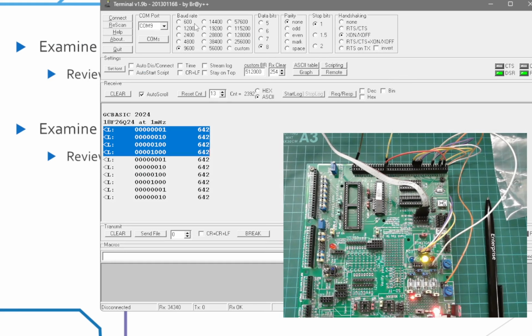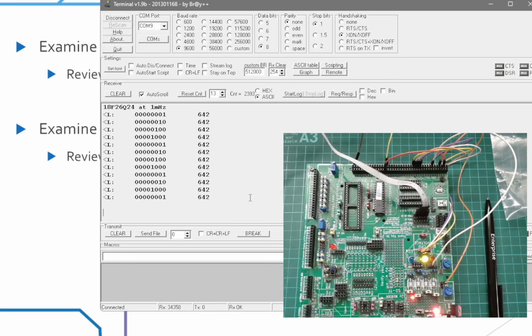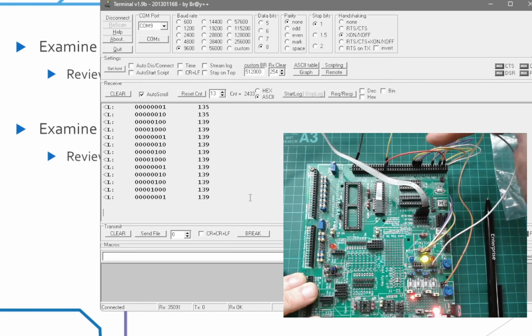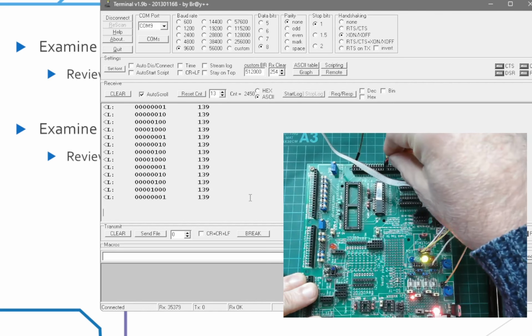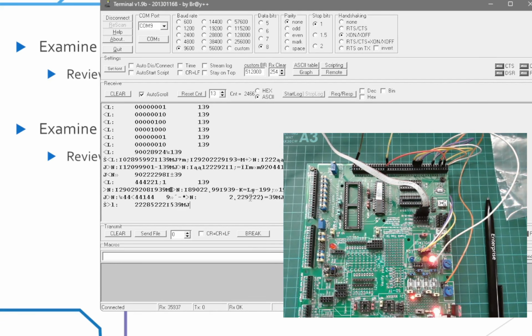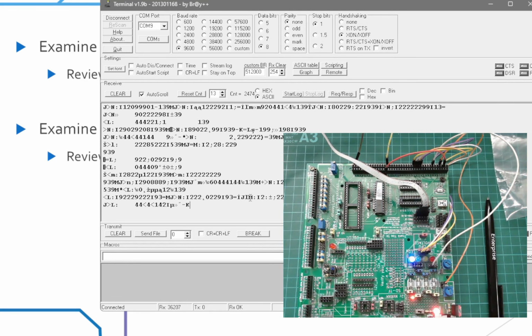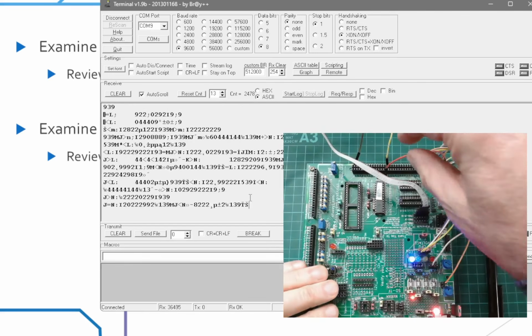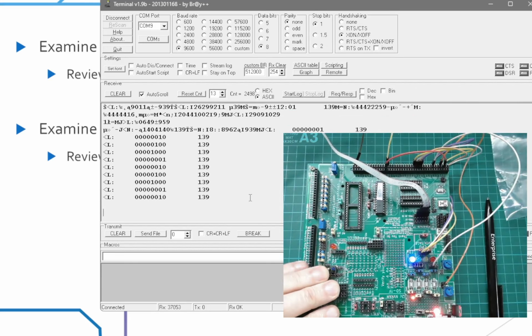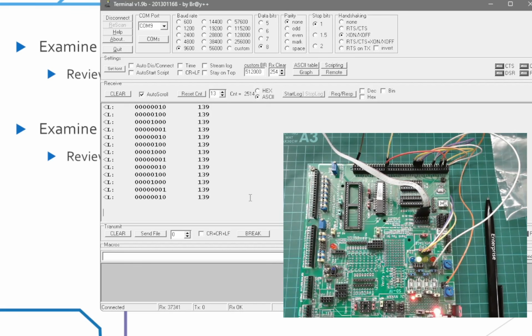Now, I will restart this, and you can see that that is rotating quite nicely, and that's happening quite fast. I'm putting it down to 100 milliseconds-ish, because it's all ish, isn't it? There we go. Power domain is connected. Watch. I will disconnect the power domain. You get gibberish on the terminal because the voltage is not consistent. Let me reconnect that. On my board, I'm quite fortunate, I've got this capability. And the moment I reconnect the power domain, the voltage inside of that internal circuit becomes correct, and it all works.